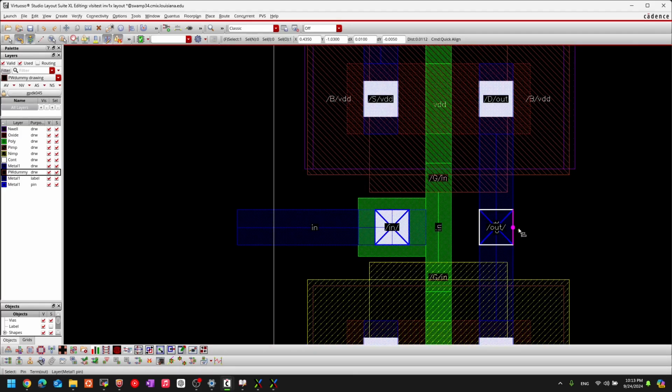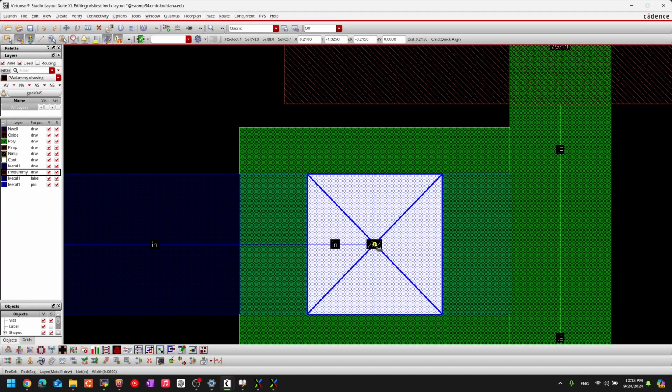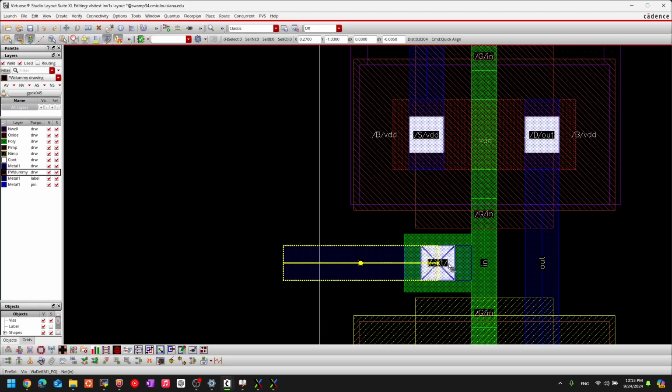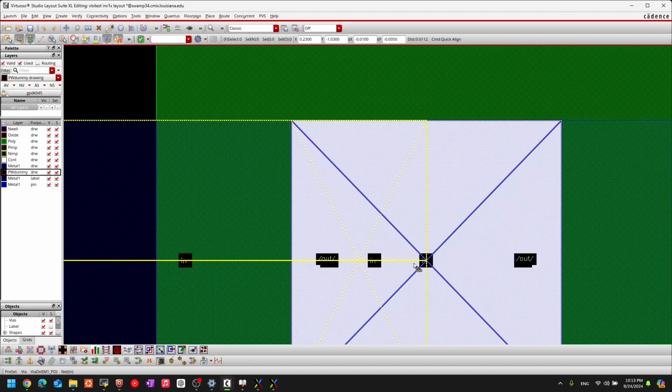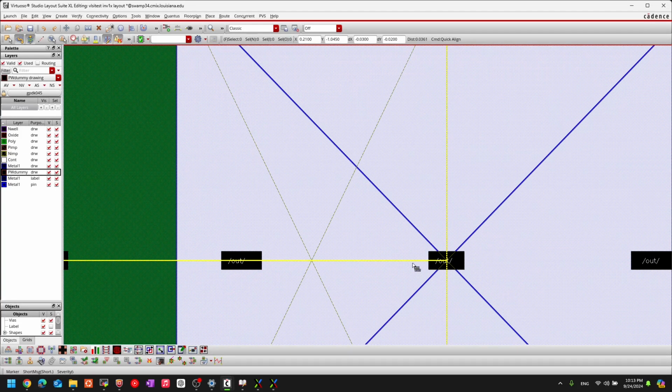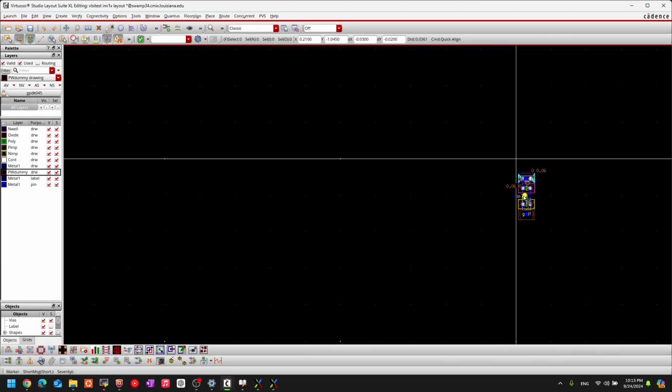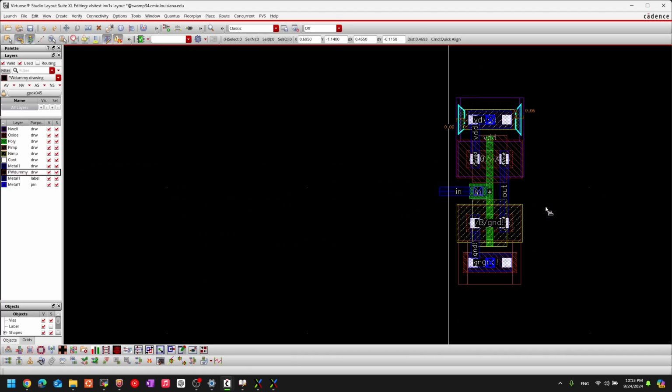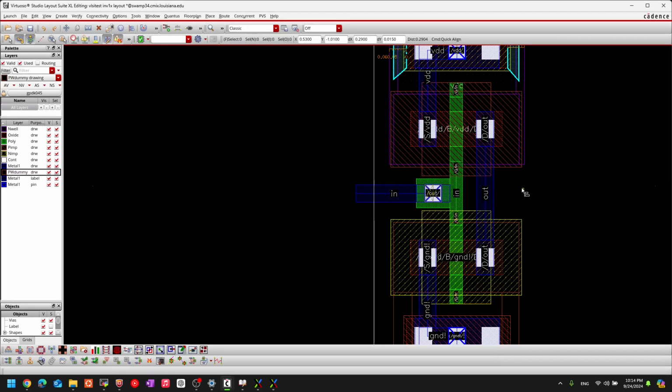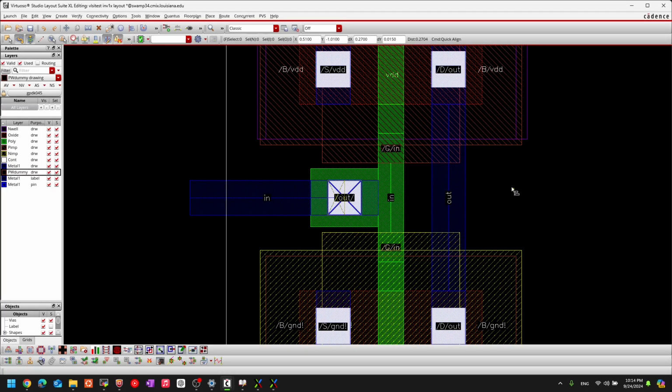So once you select the dot and select another dot, just as this one or maybe this one, I just move the out pin on top of the in pin. And this is creating a violation right now. So yeah, that is another way to align a pin or a strategy to move pins around or objects around.